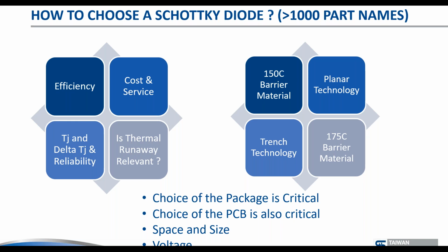All the package choices we showed before on the back end are available here, whether it's wave soldering, multi-layer boards, exposed pads; power density is also important. I should also mention that the way you answer this question depends on the voltage, whether you're using a 40 volt or a 200 volt diode. So this is no longer an easy subject. It becomes quite complex to choose a rectifier or a Schottky diode, combining the advantages of the technology together with the commercial aspects.